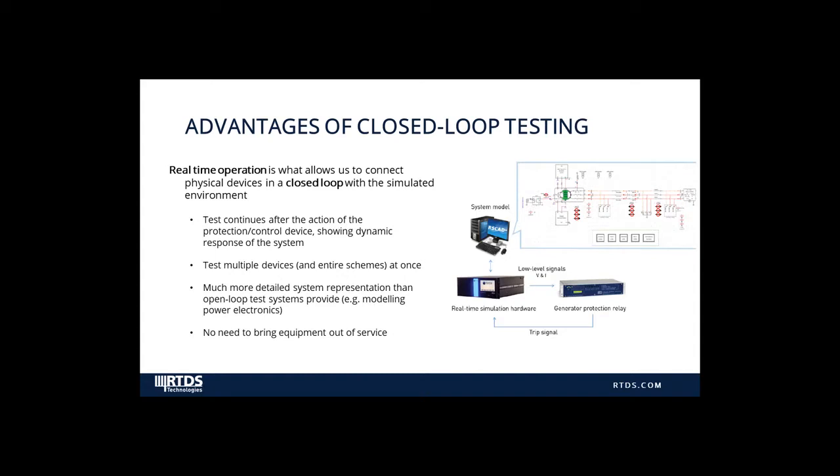This type of testing, also called hardware in the loop or HIL testing, is only possible if we are updating the inputs and outputs of our simulation continuously in real time. It's not possible with a non-real-time modeling tool or with open-loop testing tools like a relay test set.